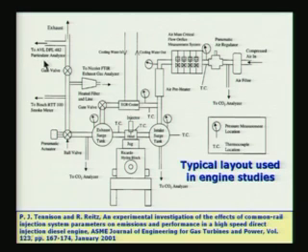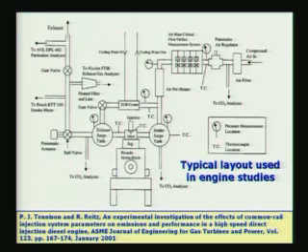Of course, we have not covered a discussion of particle size measuring devices. They usually operate on the principle of the scattering of radiation from the particles, and by looking at the scatter pattern of the particles, one can get an idea of the diameter and the distribution and so on. So this is the particulate analyzer.